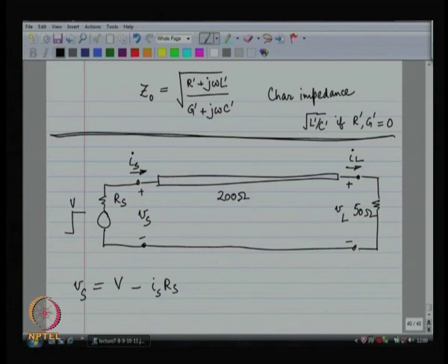Remember, Kirchhoff's law is always satisfied, no matter how hard you try, it is very difficult not to satisfy Kirchhoff's law. In fact, if a physics person claims to you that Maxwell has an extra term which makes Kirchhoff's law not being satisfied, say that it is still called a displacement current. So, if you call it a displacement current, that extra term in Maxwell's equations, Kirchhoff's law is once again going to be satisfied. It is very hard not to satisfy Kirchhoff's law, and even inside the transmission line Kirchhoff's law is going to be satisfied.